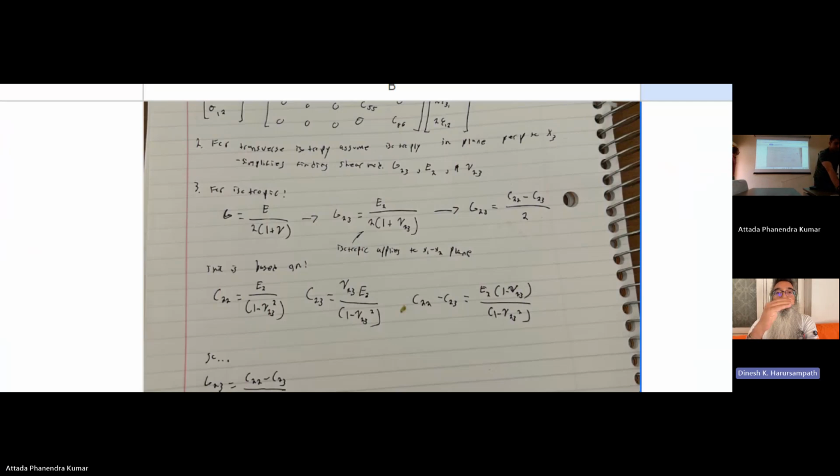So I want you to look at, for isotropic, whatever you have written there, G equal to E by 2 into 1 plus nu. Look at that derivation and then substitute for all those quantities in the derivation with the ones using the appropriate subscripts that we have for the anisotropic, or rather orthotropic material, which is also transversely isotropic. So this becomes kind of trivial if you just use G equal to E by 2 into 1 plus nu as a known equation. Okay, that makes sense. I can just derive it starting from before that. Exactly. Yeah.